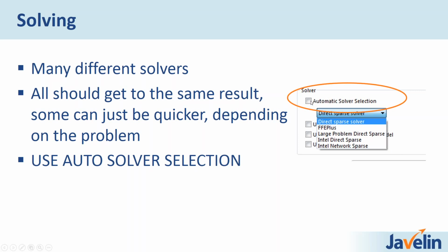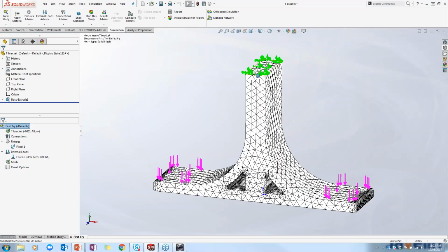Based on your setup, the number of contact sets, the total degrees of freedom of the model, things like that, SOLIDWORKS is going to pick the solver it thinks will work best. And for new users, that's definitely the best option. So that's all I'm going to check here.